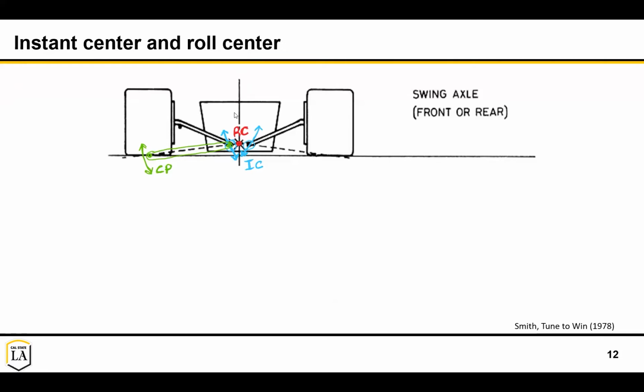And so what we'll typically do is put the roll center closer to the ground to minimize the jacking and accept some of the roll, but control the tires so that they maintain adequate angles with the ground throughout their travel, which can be easier said than done.